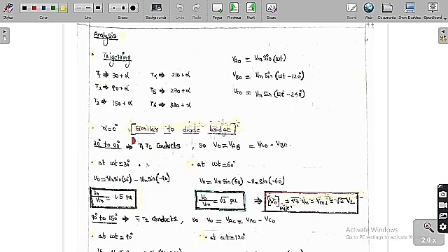Now suppose alpha is equal to 0, for any load, I want to figure out the output voltage. Alpha equal to 0 means these thyristors become purely diodes, similar to a diode bridge. Now I want to see the nature of the output from 30 degrees to 90 degrees.